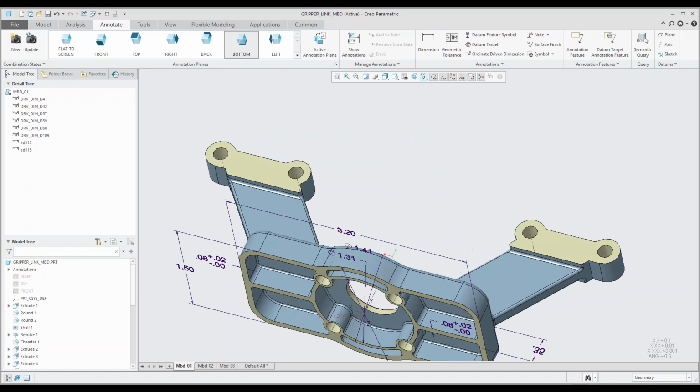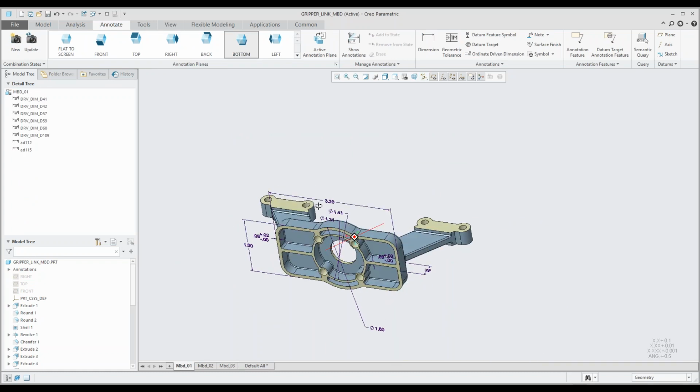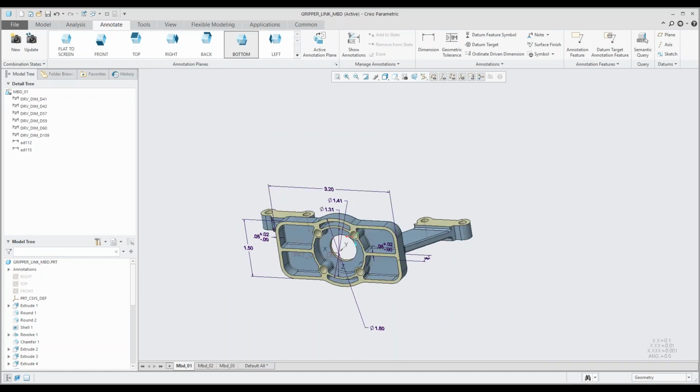So you'll have to start thinking or planning the way that you want to approach your 3D annotations. Think about a 2D drawing. As soon as you start that, you'll normally have your front view. Where will you place that? In the left-hand top corner, or the right-hand top corner, or the bottom, or wherever. That's a planning process that you're working through, and we've been using it so much that you actually don't think about it.